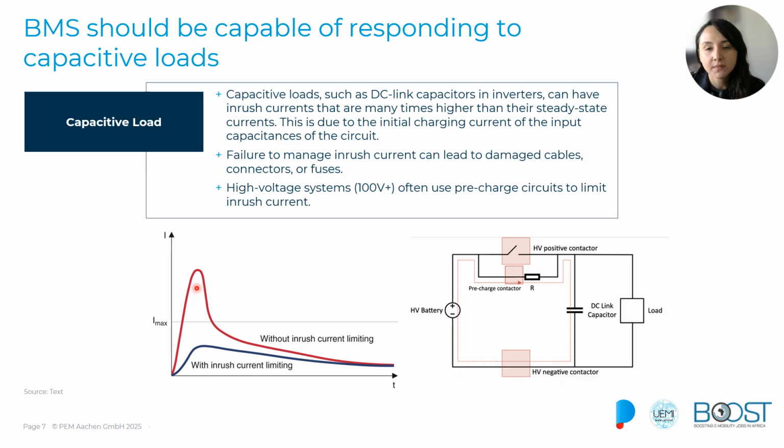And the BMS must be capable of managing these high currents and limiting that current. Without the management of that, this can lead to several issues. For instance, we can damage components like the contactors, the connectors, the cable. We can blow fuses of our system, leading to costly repairs.